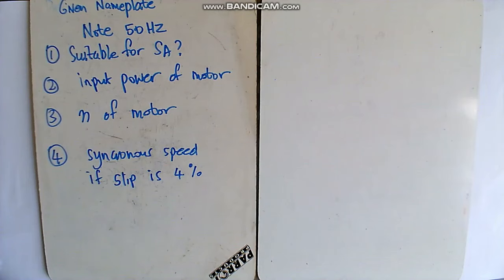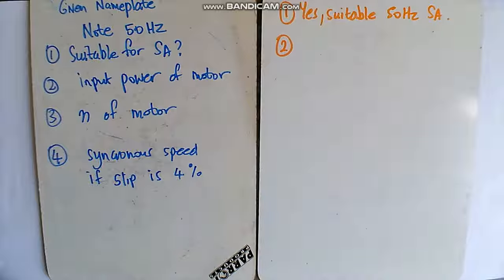Right, first question, is the motor suitable for SA? Our answer is yes, because of 50 Hertz, 380 volts. South Africa uses 50 Hertz. Our next question said calculate the input power to the motor. So input power, don't forget the formula, and this will be true power. Best to write the formula out with multiplication in between. With all the stress, you don't want to make a mistake.